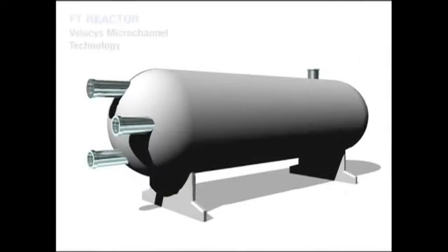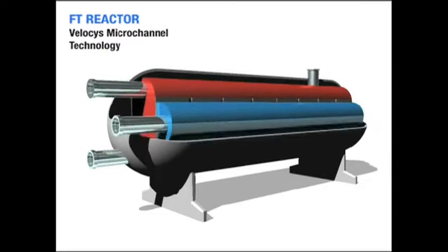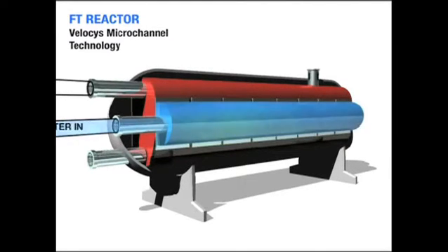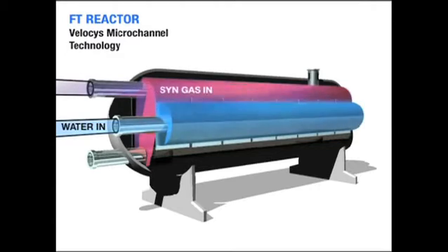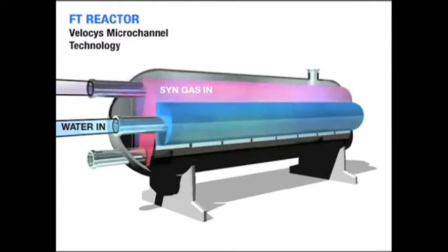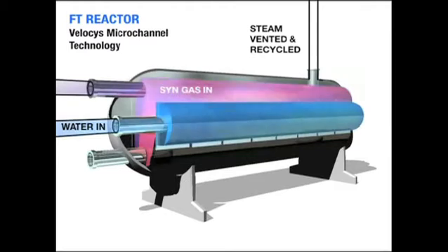Conventional FT reactors can tower to over 200 feet tall or 60 meters, while microchannel FT assemblies sit horizontally and measure only 5 feet in diameter and are 25 feet long or 2 meters in diameter and 6 meters long. Headers pipe in coolant water and synthesis gas and evenly distribute flow to 10 reactors in each assembly. Liquid water flows horizontally into the cross-flow microchannel FT reactors and exits as a two-phase mixture of water and steam. The steam is vented through the top of the assembly.